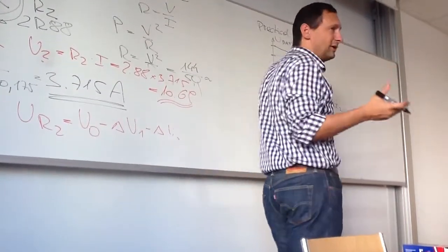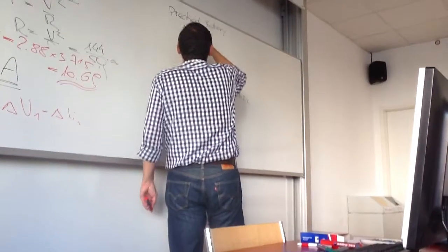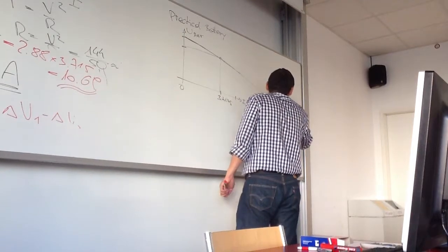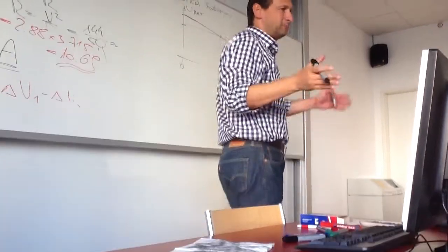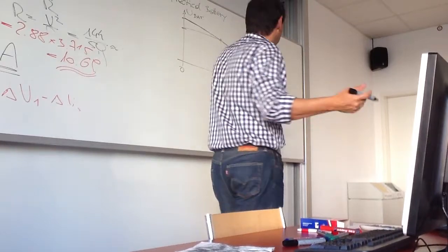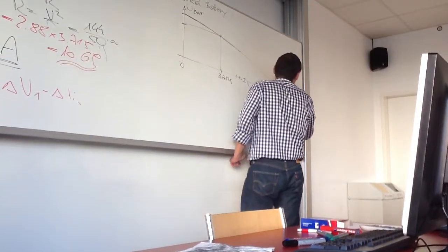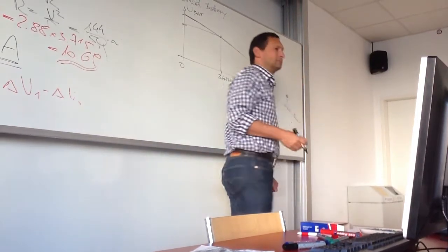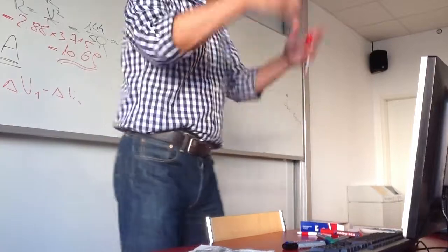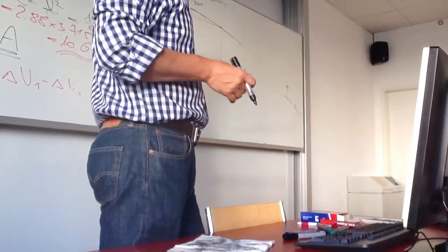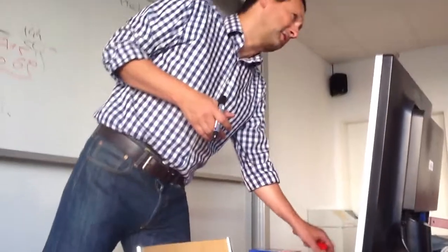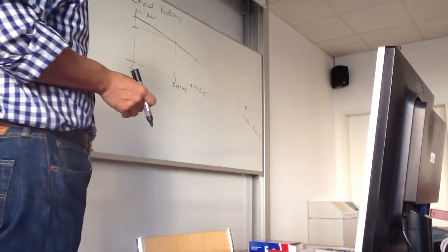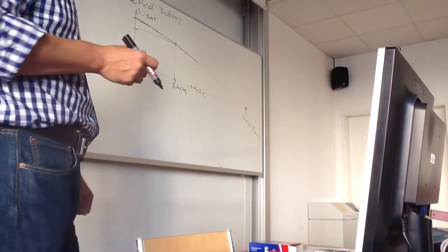What happens if you short circuit the battery? Then you go along this load line until the voltage is 0. And if you do this with your car battery, that gives you a spark. It might be 600 to 800 amps. So if you use a normal wire, then the wire will explode. The battery from the remote control, it's okay, no problem. Except that the battery is gone. Yeah? If you short it one time, then it's gone.